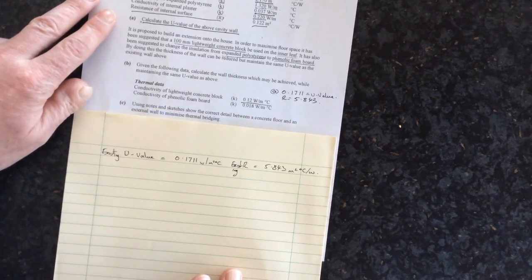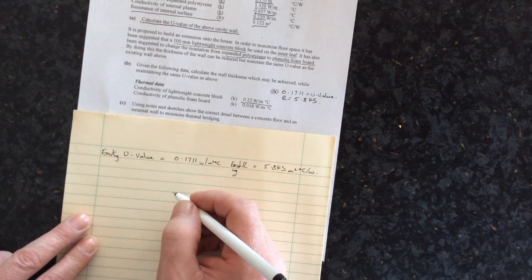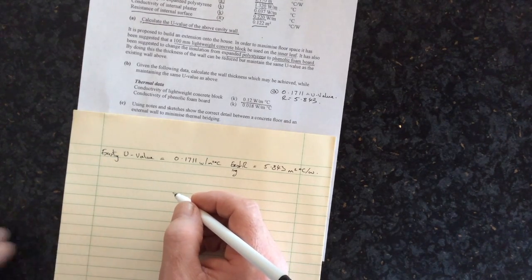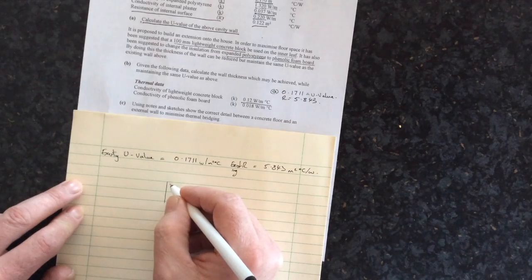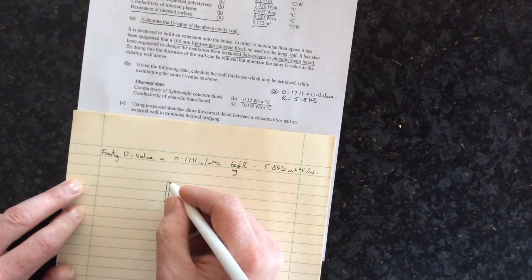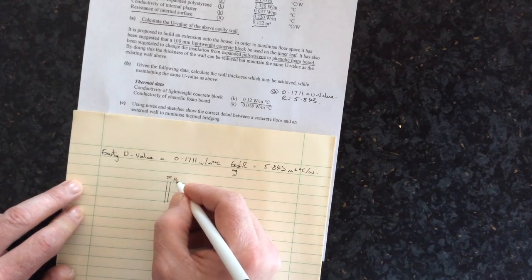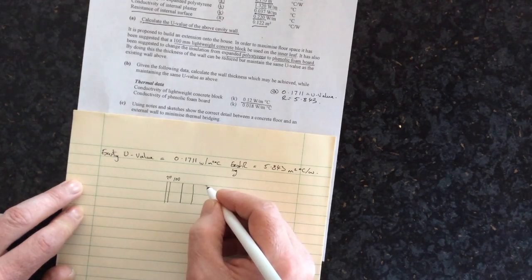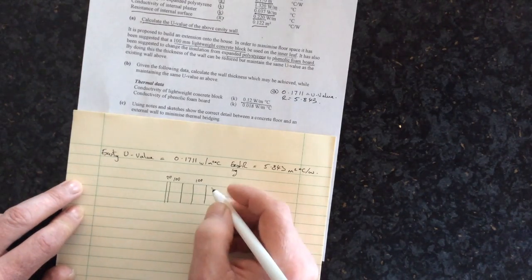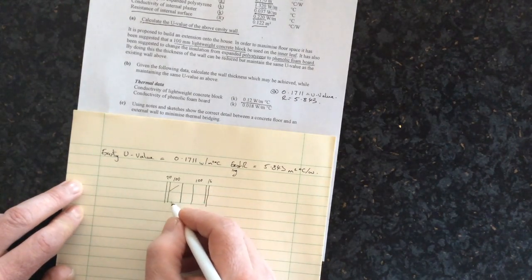Right, so just to give you an idea of the structure again. The first thing we're going to do is calculate the resistance of the wall when there's no insulation in it at all. So we're going to have our external render, which was 20 millimeters. We're going to have our external leaf, which was 100. We'll have our cavity there. We don't know what thickness of cavity we have yet. We'll have our internal leaf, which is 100 millimeters lightweight concrete block now, and 16 millimeters.